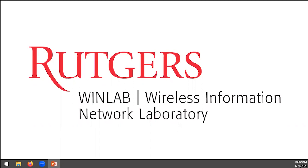Yeah, because in general, as I told, when you are using PIN diodes, you should have some off time period, right? In this off time period, in each branch, you don't send the signal, in comparison with a conventional phased array that sends the signal all the time. But maybe there are some techniques using optimization algorithms to make it more efficient. But I don't think there is a way to achieve exactly the same performance in the desired angle, because we are losing some power in comparison with the conventional one. By doing time modulation, you will miss some power in the off time period of the PIN diodes.